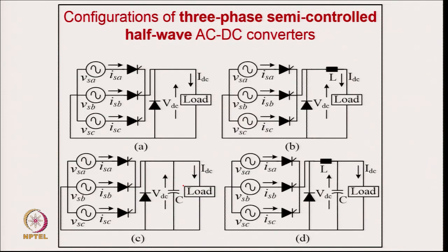And then this is semi control, of course half wave semi control, but it also draws the DC component. You have control of the output voltage from 0 upward, but it has very poor power quality because of the control. You have phase angle control, which takes reactive power from the supply, as well as harmonics, and not only harmonics, but even a DC component from the supply system.